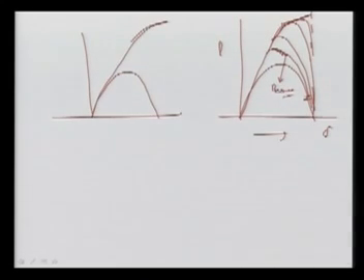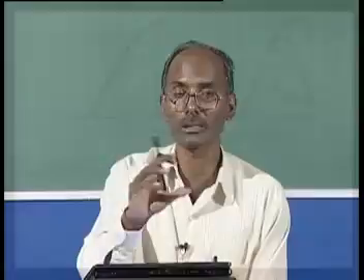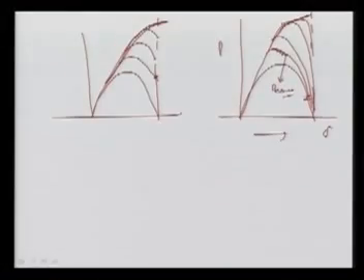This is without, meaning infinite limit. If your system hits the current limit, what we are going to get here is not going to 0. Mind it, the only difference here is that this is going to 0, because now we have a simple inductance. The inductance is fixed, the variable part is 0, and finally we have to come here. Here we are injecting IC1 max, here IC2 max, and the IC2 max is more, and then we get this characteristic.